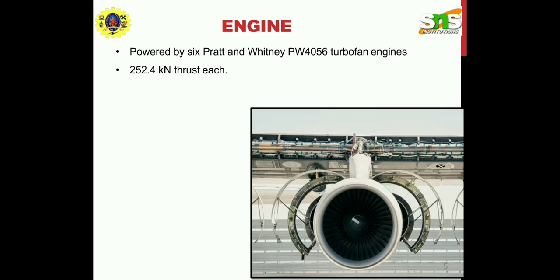And these are the engines powered by Pratt & Whitney turbo engines, which will be used in the principle of turbo machines. When the path of the flow is wholly or mainly parallel to the axis of rotation, the device is termed an axial flow turbo machine. The radial component of the fluid velocity is negligible. Since there is no change in the direction of the fluid, several axial stages can be used to increase power output. A Kaplan turbine is an example of an axial flow turbine.